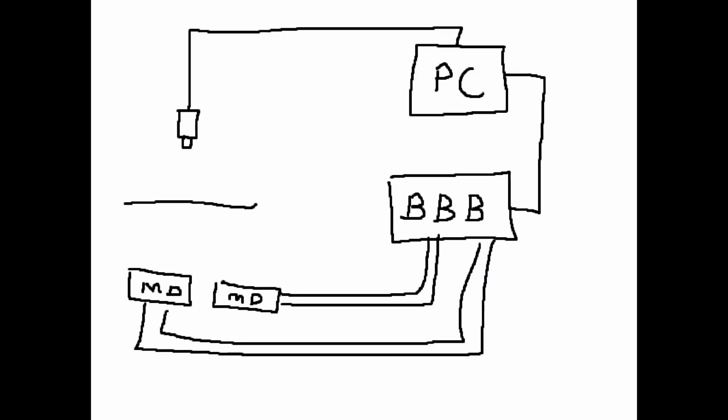Here are the motor drivers. The output waveforms, be they pulse width modulated or stepper signals or something else, along with the direction signals, are fed into the appropriate driver module. These generally consist of commercially available driver modules mounted on a custom created PCB. The circuit boards are created with the Line Grinder software, a PCB isolation routing project I have created. Line Grinder easily creates PCBs like that. This saves the time and expense of paying a board house to produce them.